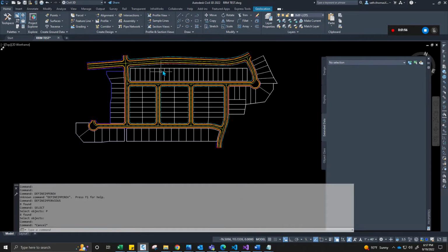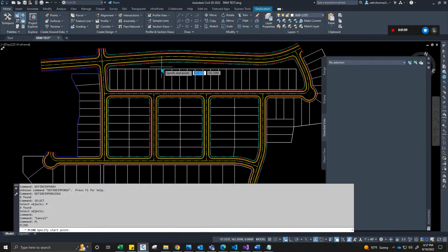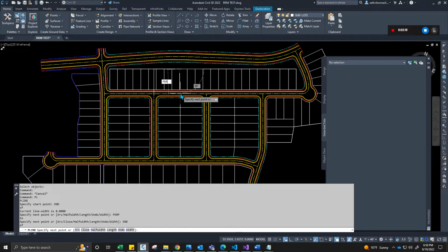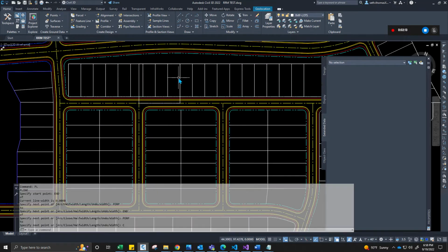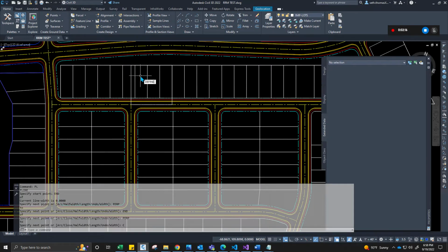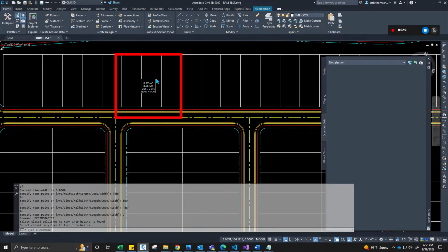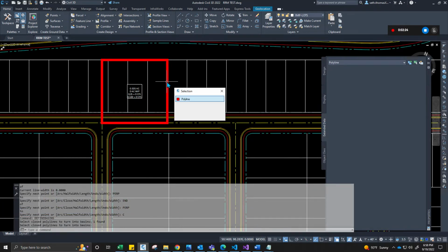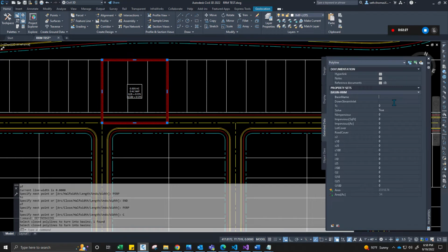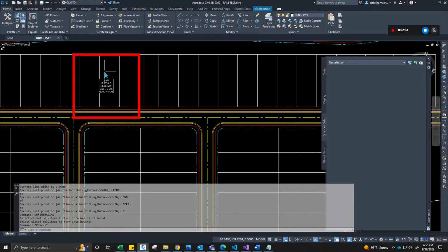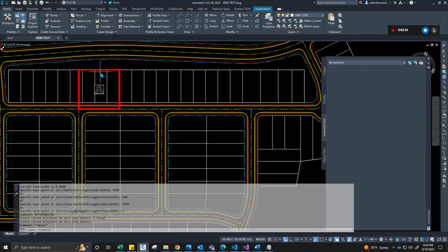So now that I've defined my impervious cover, I'm going to define a basin. So I'll just draw one along these lots here, and close it with C. And then I can type define basins. And that's going to create a basin object with a tag on it, which correlates to the data that we have in our property set. So I'm going to call this one A01, for just how a typical basin of a storm network would be named.